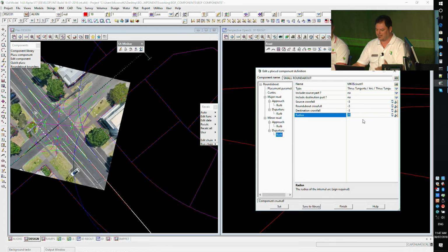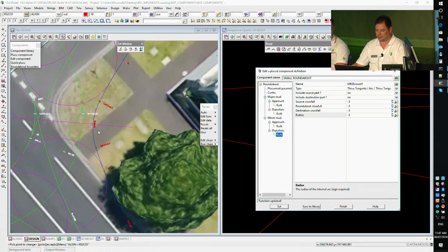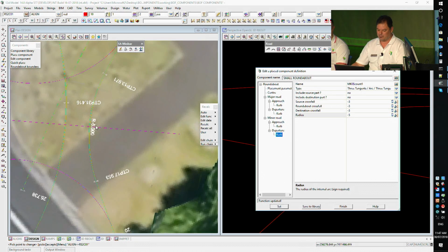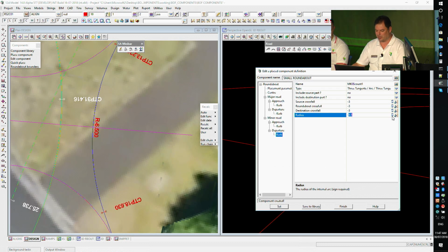with this radius. And obviously a positive radius for this is too tight, it's never going to work. So you can go negative with these values. If I typed in -5 on that and hit set, you'd see you get something a little bit more reasonable. So it's still doing the arc 3 tangent, but it's now placing this -5 in there. And then you could go around with the spinners and play with that until you got something that maybe satisfied one of your turning movements on there.